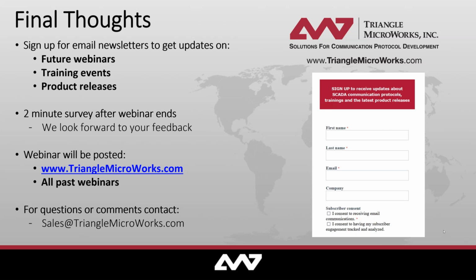Those security mechanisms can apply to layer 2 GOOSE as well. You can apply authentication and encryption using KDC, or a key distribution center. We have a lot of information about that on our website. We actually sell a protocol stack version that includes support for that. But that's the short version: if you're using routable GOOSE, then it's designed to leave the substation and be routable. If you're using layer 2 GOOSE, then you would need a tunnel or VPN. Otherwise, you need a flat network in order to have those messages go out on a wide area network.